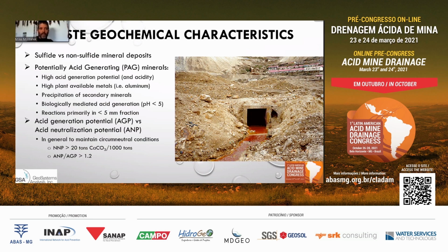For example, you may have high neutralization capacity, but if you have high acid generation potential, those minerals will start to oxidize, generate acid, and they may be neutralized, but what you have is a very saline system. So in a semi-arid environment, it then becomes very difficult for plants to grow in that material, even though it may be circumneutral and have a high pH.